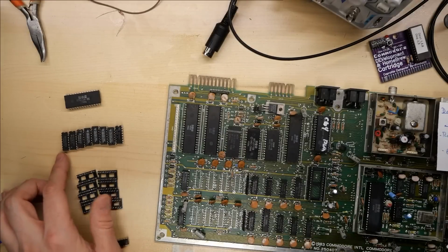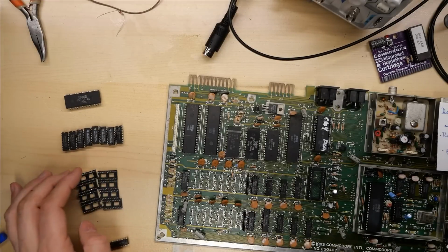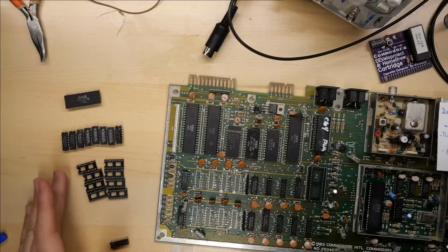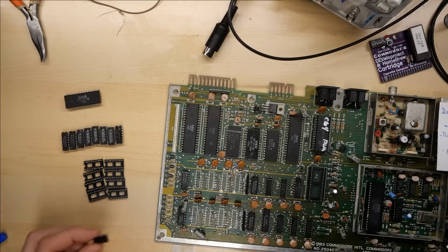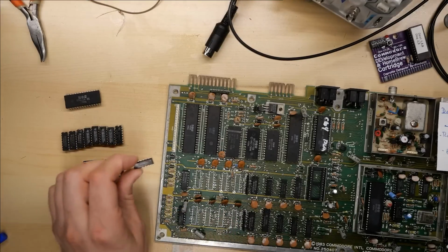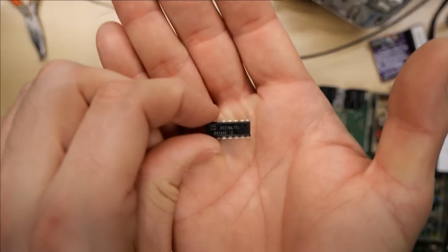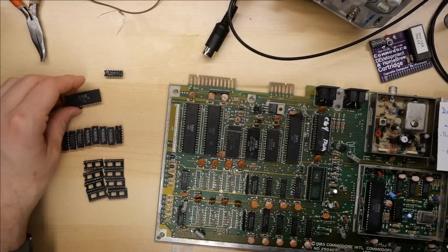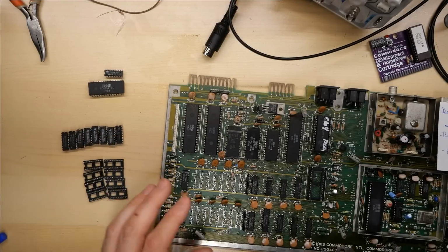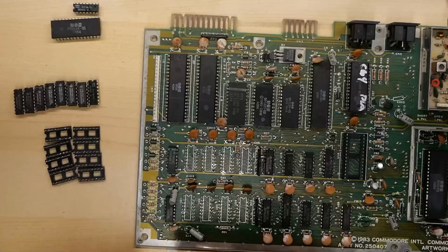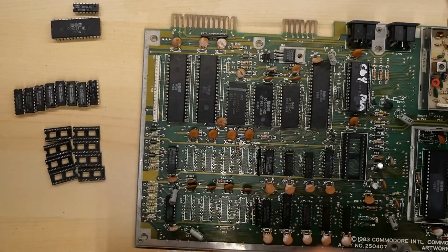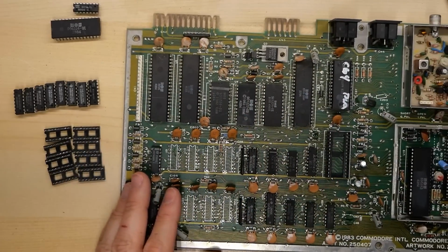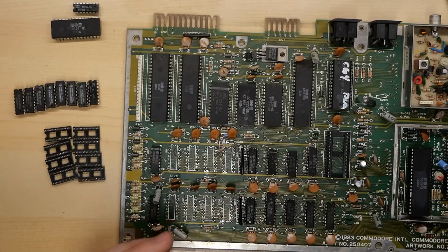None of them are MT brand. These all work fine in the full RAM test on the other machine. I found 8 sockets here for this board. And while I was searching for those, I actually found one more bad RAM chip. This one here is an NEC branded one, so that's bad. And then of course, here's the original bad PLA that was in this machine. So let me pop these sockets and this RAM into this board, and then we can run a full diagnostic on this thing and see if it's fixed.